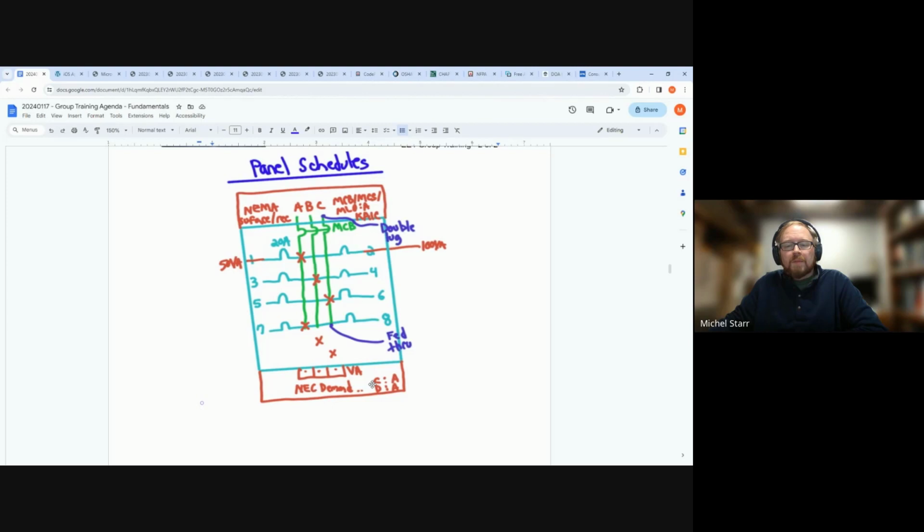So that helps. And then if you have a lot of panels that all have receptacles, and then you connect all of those to another panel, well, then that panel gets the benefit of this demand consideration, given how many receptacles are connected to that panel now. Well, 100% of the 10 kVA, but then 50% of the rest, which might be a reasonable reduction.